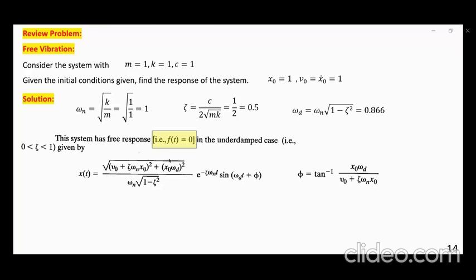So this is the amplitude of the vibration, which gets smaller and smaller and smaller because of this exponential. And of course there is a phase, we call that phi, involved. So please check your notes. If you plug these things in, x naught is 1, v naught is 1, plug it in, you're going to get A equal to approximately 2, and phi is approximately 5.524.